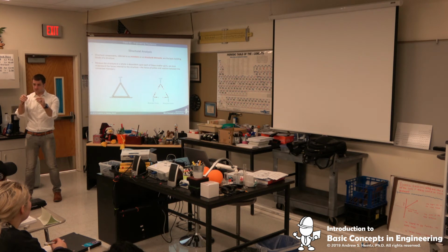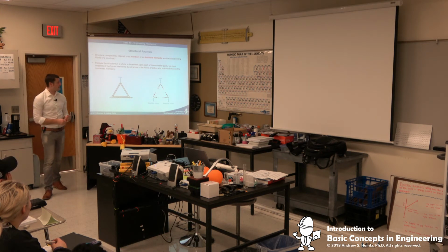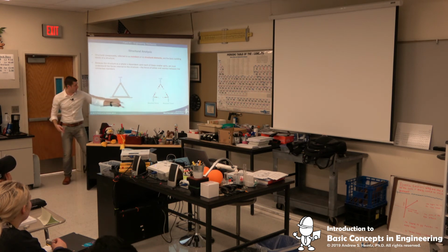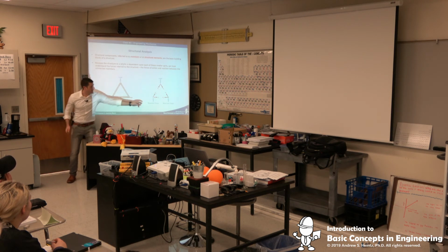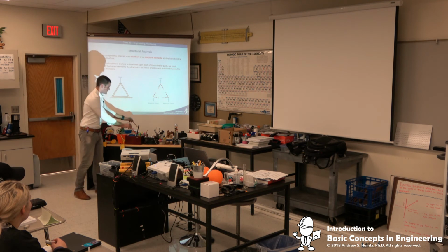This one is under compression, it's being compressed. This one's under compression, it's being compressed. But the bar here that's holding them together, it's actually being pulled apart. And it has to be able to have a tensile force that can hold that structure together. Right? So that's what we're looking at. We're looking at a compressive force here, and that's why the arrows are going towards each other. Compressive force here, and then this guy is being pulled apart. Okay, and that's what we're going to start doing when we go into structural analysis.